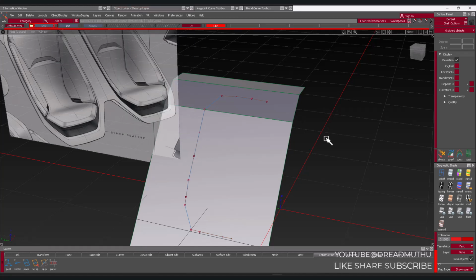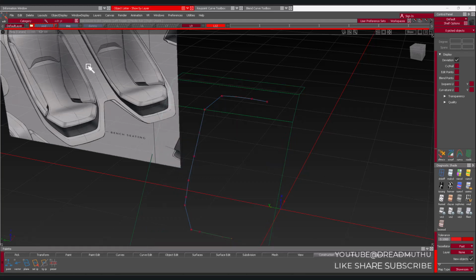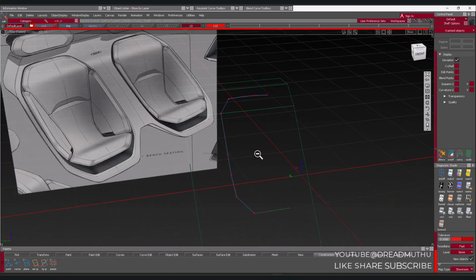So at this stage I would save it as a new file, and I will delete its history, so that if we accidentally do any modifications in the curve, the surfaces will not be disturbed. So yeah, I saved as already.